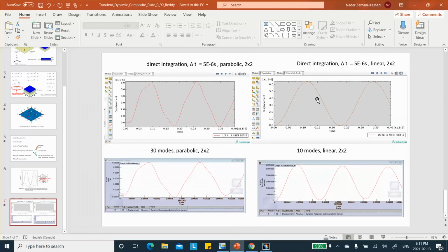If you do the problem with a linear element, either in Abaqus or in CATIA, of course, these relatively are close to each other. But these are of course much better. So when you go with a poor element, few of them, then don't expect a miracle. But at least when you go to parabolic, they're now close.